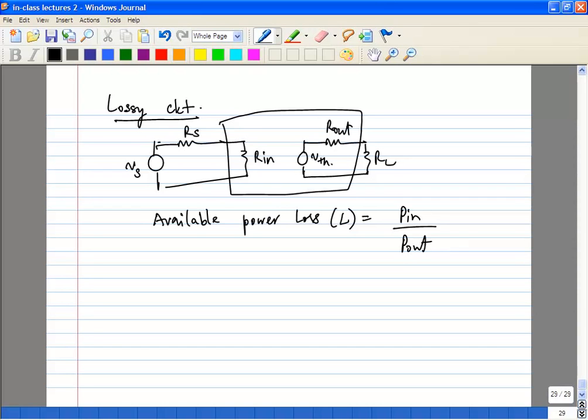It's exactly the opposite. A matched condition is assumed. It's basically 1 over AP of that. So what you'll find is, for LNAs and other things, you'll specify gain in dB, like 15 dB or 20 dB, whereas for lossy circuits, the loss is defined as like half a dB or 1 dB. It's actually a negative power gain. That's what it is.